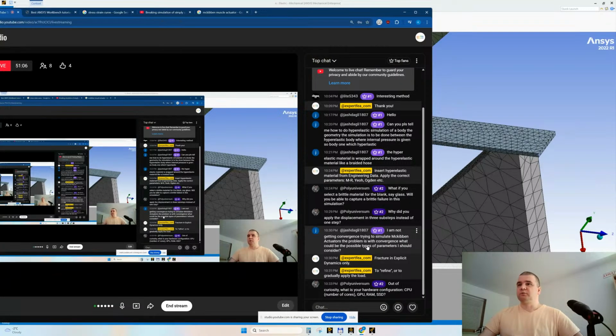The parameters should be defined by your material supplier, either Ogden, Yeoh, or Mooney-Rivlin, whatever. Also be very generous with the ANSYS settings. Define very small time steps. This is my answer for you.